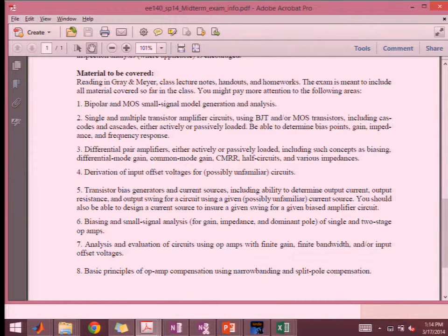We talked about biases and current sources. So again, understanding what's the minimum output voltage that the source presents to the load, what's the systematic gain error, where that comes from, different topologies, and knowing how to analyze and go around the KVL loops in these topologies. That connects to the biasing. Again, how do you bias such a source? We did the triode device bias and all these other things. Sizing the device larger gives you smaller overdrive, or sizing the device smaller gives you larger overdrive, so you can get an overdrive multiplier, right? These kinds of concepts.